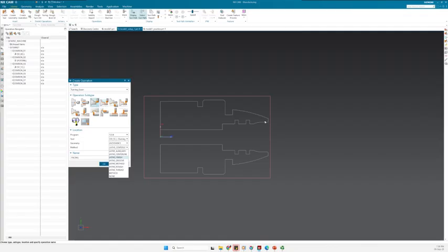But in this specific case, it's only, I guess, if I'm not mistaken, yes, 3 mm material to be removed there. Diameter is so small, so I'm going to do right away the finishing. In case you have some different operations for finishing, you can just make an underscore and, I don't know, call it rough 1, rough 2, finishing or something. But in this case, I'm going to have only facing. The better you are at renaming your operation, the easier it is for you to follow it later, and also for anyone working on your program or for the operator to figure out what you actually intended to do. So now this is facing, I'm going to have one facing only.